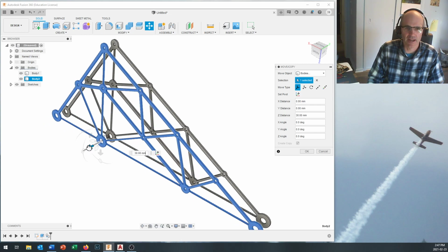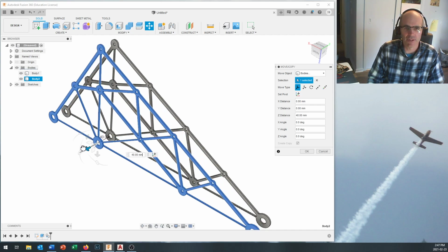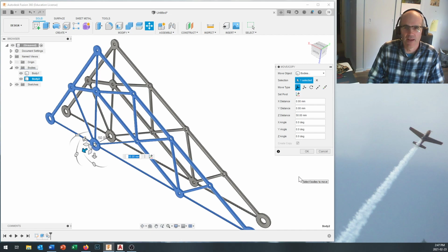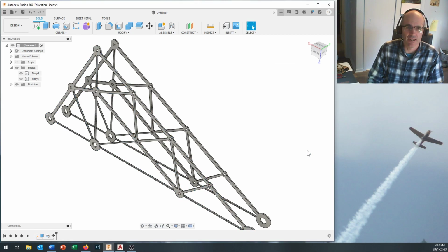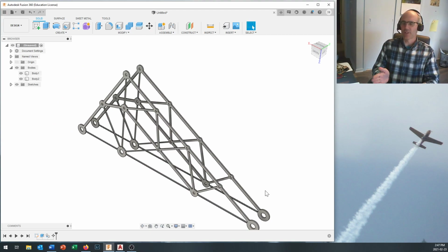You could do narrow. You're allowed to go right down to 18 millimeters wide. So you could take it down, and that's going to reduce the weight of all the dowels that you have coming across right in there. So you can try lots of things. I'm going with 50 just because we tried that in a lab previously, and you've got to start somewhere. All right, so now we've got these two sides, and we need to join them together with pieces of